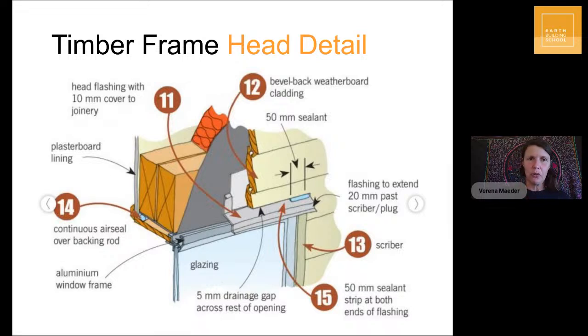Because the timber construction, you already see this, has many more different materials installed in layers. And in timber construction, if you have ingression of water, you can get rot. That eventually will destroy your building, so it's not safe from a structural point of view, but it also creates a real big health hazard. So you don't want to have a leaky building at all. And the timber is actually, in a way, not more problematic than the earth, but if the earth gets a little bit wet, it just dries out. It never rots. It doesn't grow mold.